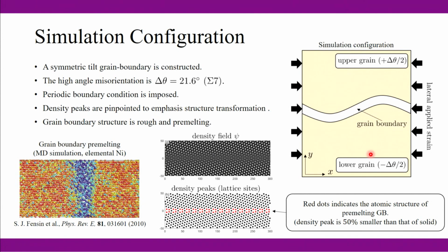And we know the growth rate usually depends on the wavelength. If two solids have different elastic properties, then different wavelengths of that surface undulation will give different elastic energy differences. So we will also change the lateral dimension to see, for different kinds of grain boundary perturbation, whether the grain boundary will always remain stable or sometimes become unstable. Did I answer your question?